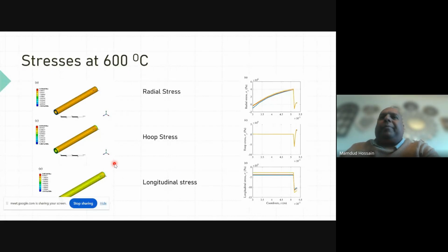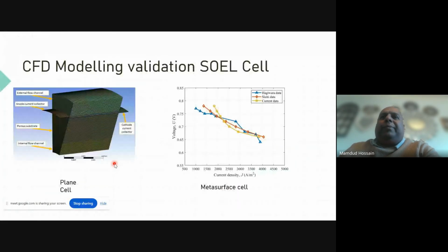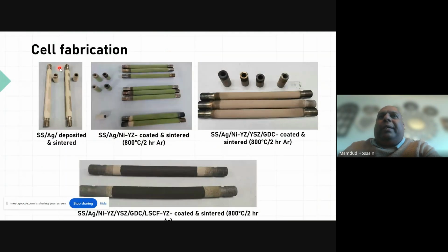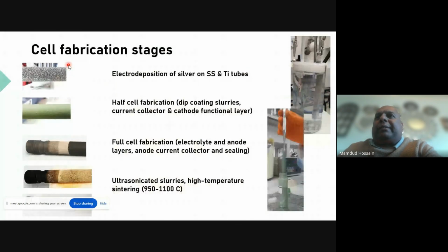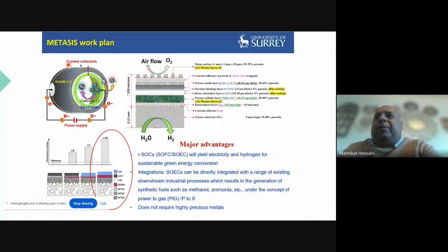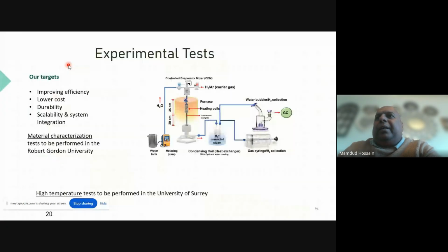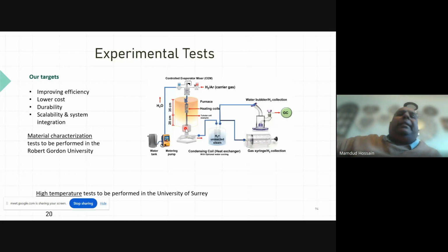So when you are holding our tube, if you look at our tube here, we actually have two screw connections with two ends, but when we are doing our experiment here, we don't fix both ends. We have to keep one end free and one end screwed, so there is space for thermal expansion.